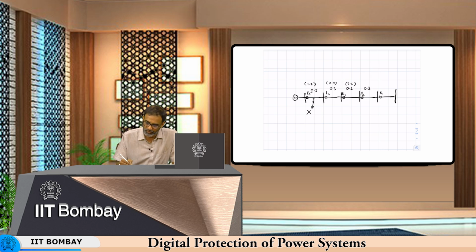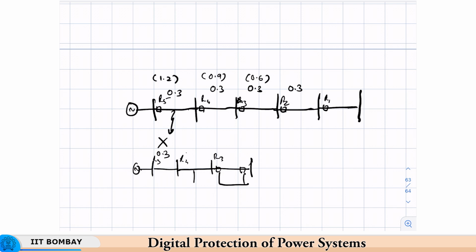So, what you will probably need to do is, for one section somewhere, use a pilot wire or a differential protection, say here in this section, say this is R5, R4, not necessarily here, but just for the sake of example. Then you can start the coordination afresh. This can again be set at instantaneous value, and then this will operate in 0.3 seconds.